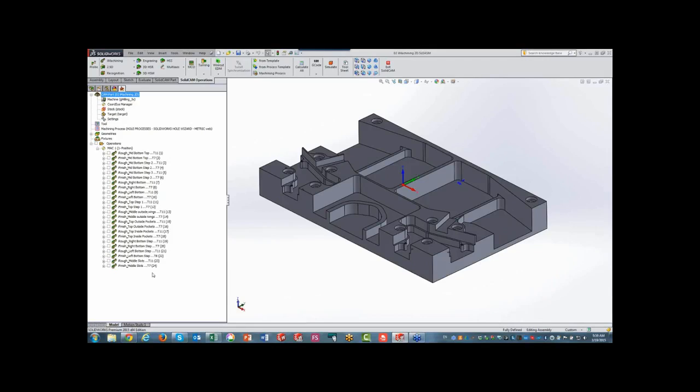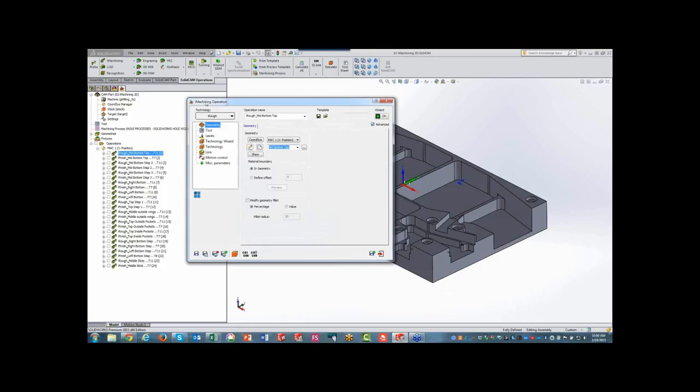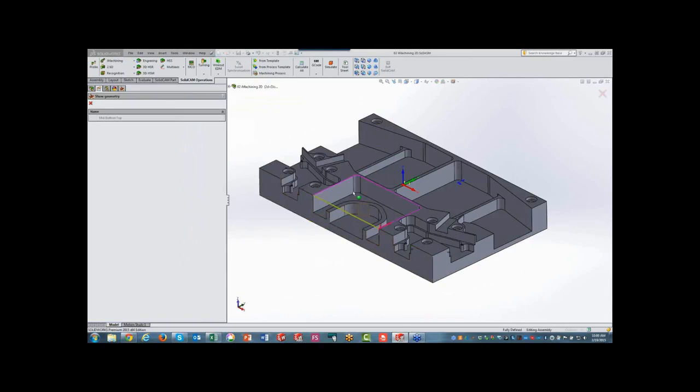I still have to study the part exactly the same way I did in the 2.5D operations. There's no difference in that. You can take a look even if I were to open up the first operation over here. You can see I'm in iMachining. I have my geometry, just like I had my other part, the exact same geometry. And again, I had to study my part to see exactly what I have to do over here. So again, remember, studying the part is part of your programming time. And there you also have to make sure you're not making any mistakes.